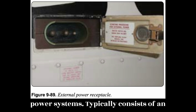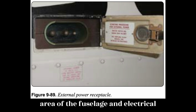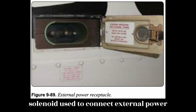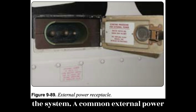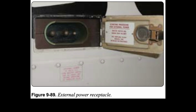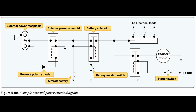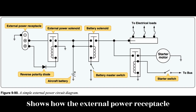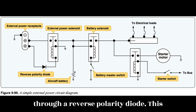The external power system typically consists of an electrical plug located in a convenient area of the fuselage, an electrical solenoid used to connect external power to the bus, and the related wiring for the system. A common external power receptacle is shown in Figure 9.89. Figure 9.90 shows how the external power receptacle connects to the external power solenoid through a reverse polarity diode.